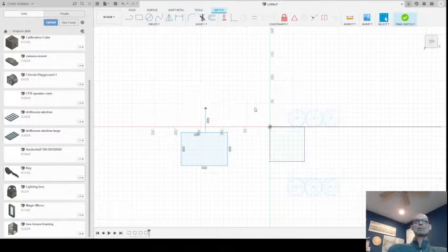Excuse me. And now I want to make sure that I exactly bisect this line edge. So I can go to constraints and find the midpoint constraint. It constrains a point or object to the midpoint of another object. So I'm going to go ahead and select that. Just select that line as one object, and this ray as the other. And what's it saying? Let me try this. It's saying that, I guess it's because it has this vertical constraint. So let me back up.